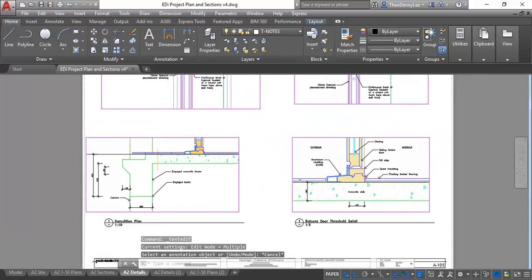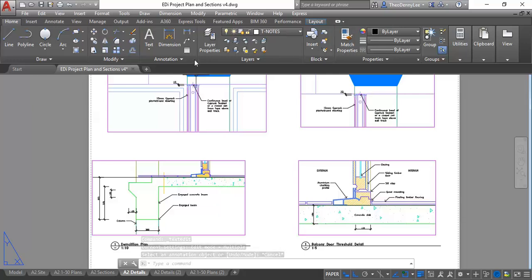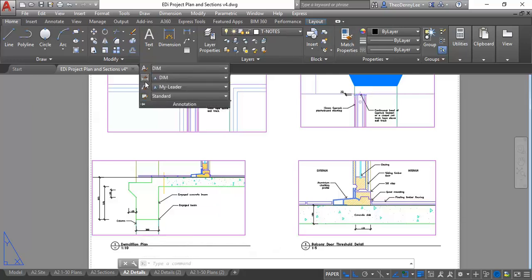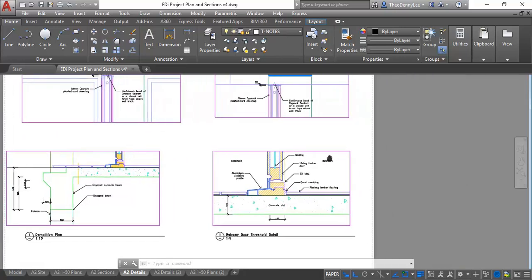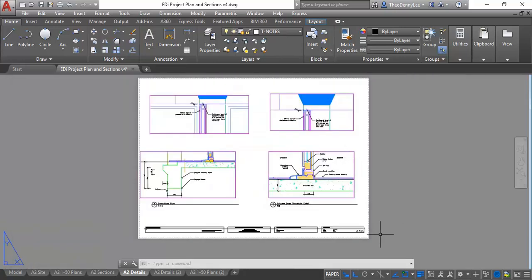Right, so that's it. Once you can work with all those annotation elements with scale, you can do pretty much everything that you need to with AutoCAD for 2D drawing. So, you know how we set the text height at 2.5, the real size, and that's for a 1 to 5 scale drawing. Is the final product, when you print it out, still 2.5? Yep. And you can check that on the sheet here. This is the print size.